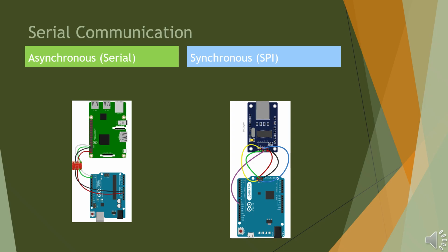The connection is straightforward. Arduino TX to HV TX on the converter. Arduino RX to HV RX. Raspberry Pi RX to LV TX. Raspberry Pi TX to LV RX. HV is 5 volts from the Arduino, LV is 3.3 volts from the Pi, and all grounds must be connected.